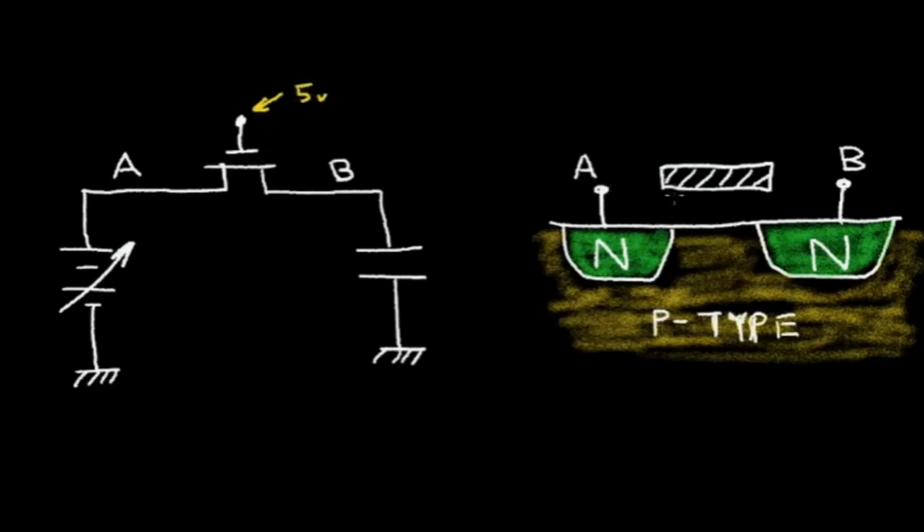I'll form an electric field here, and I'll form a channel region that will cause conduction between point A and point B. Now when this gate is set at 0 volts, the switch will be off. I'll have no electric field, I'll have no channel in the MOSFET transistor.